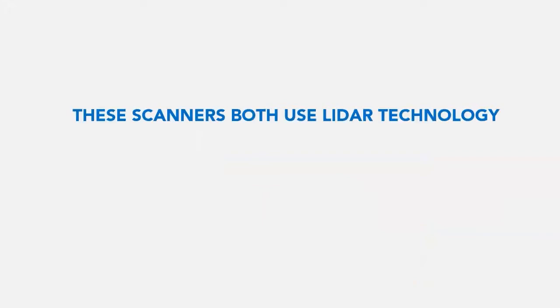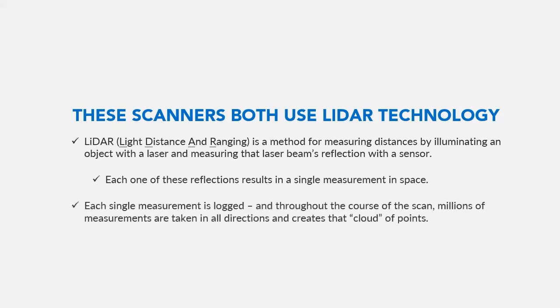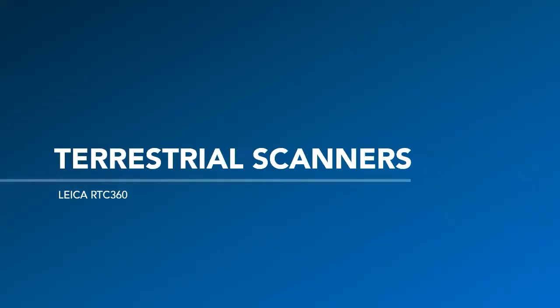So no matter what scanner you use, each scanner uses LiDAR to create a 3D data set called a point cloud. So LiDAR stands for light detection and ranging, similar to radar, which stands for radio detection and ranging and uses radio signals to measure that distance. This is a method for measuring distances by illuminating an object with a laser and measuring that laser beam's reflection with a sensor. And each one of these reflections results in a single measurement in space. And then as each single measurement is logged, throughout the course of the scan, millions of measurements are taken in all directions, and that creates a cloud of points, or a point cloud.